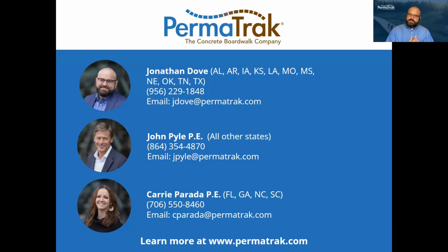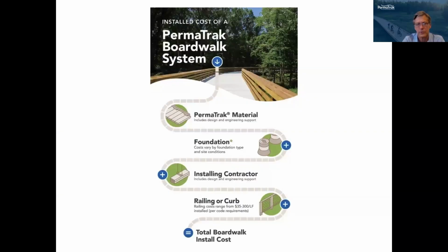Okay, great. And then the next question is around typical square footage cost for concrete systems in general. John, you want to talk through that? Yeah, so a square footage cost. When I think in terms of a square foot cost for a boardwalk, I always build out an estimate based on the total cost. So it's the material of the boardwalk, the foundation cost, the contractor's installation cost, and then the railing.